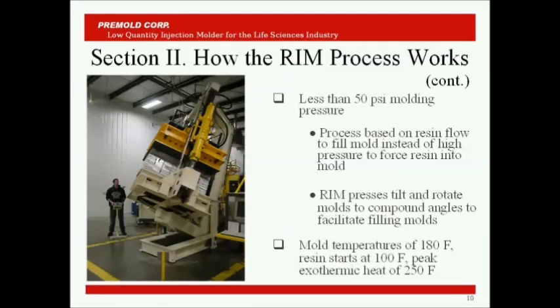What you can't see very well in this photo, because we wanted to get an overall picture, is the mix head that's attached at the lowest point or the bottom of the mold as it's oriented at this compound angle to inject the resin. The mix head's attached to the lowest point of the mold, so the liquid resin is injected into the mold at the bottom, and then the resin can flow through rather rapidly to fill the mold. Usually it fills within, a typical time would be 2 seconds. Again, you've got between 1 and 5 seconds depending on the resin system you're using. But it flows through and fills the mold quite rapidly.